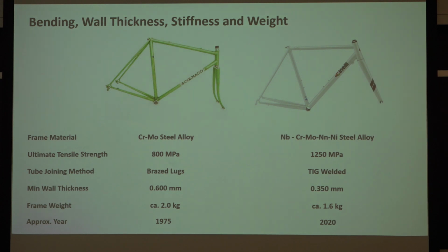If you remember from our last lecture, we talked a little bit about this, that reducing the size of grains in a piece of steel can increase the strength because you make it more difficult for dislocations to jump from grain to grain. So again, you're impeding dislocation motion. They also have chrome and moly, manganese, that's supposed to be Mn there, sorry, and then there's nickel. So this is a highly engineered steel alloy.